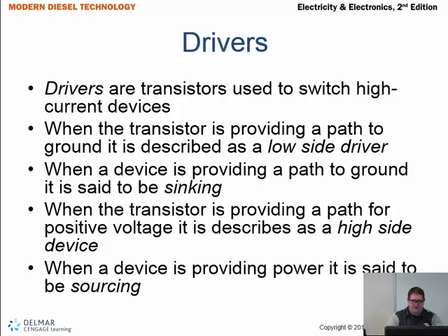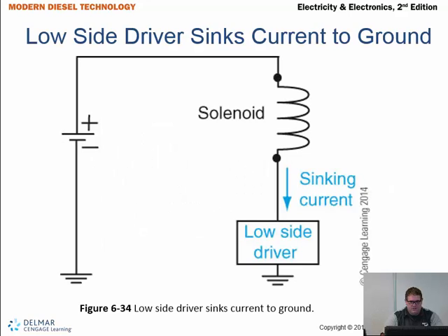When the transistor is providing a path for positive voltage, it is described as a high side device. And we'll talk a little bit about high side, low side. I think we did a little bit in one of our videos, but again, that's from our schematic: high side, low side. So positive side, negative side. So we'll talk about that. So again, it's the high side driver, it's the low side driver. Sinking, not a term I use a lot, but I have heard it. It is synonymous with that low side driver.